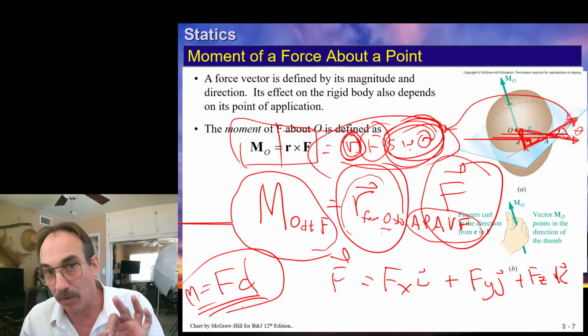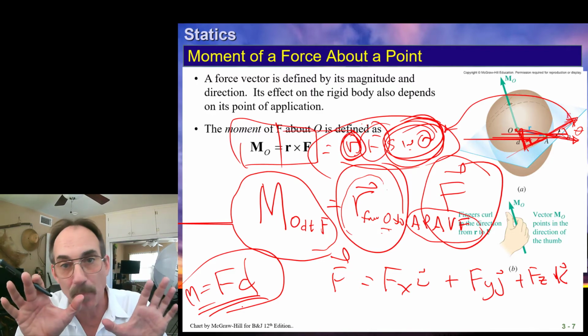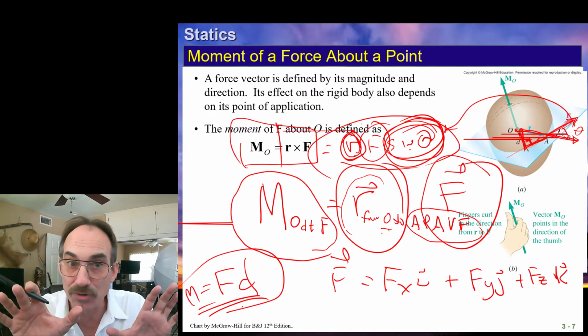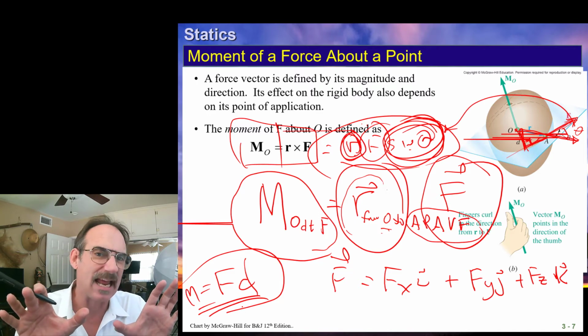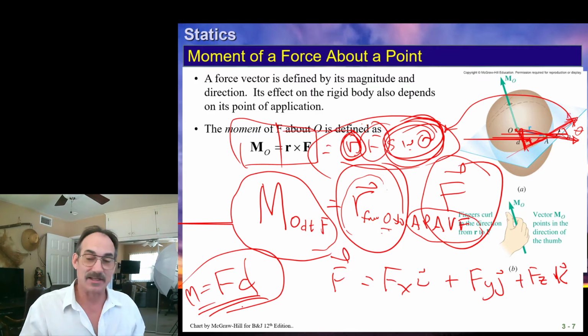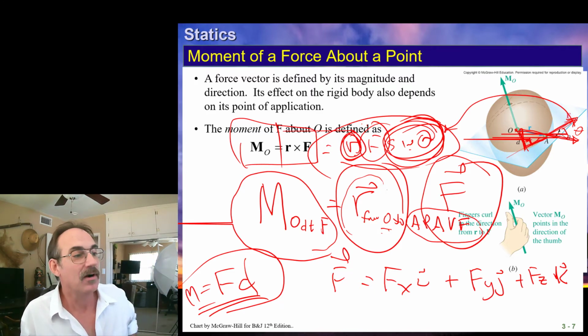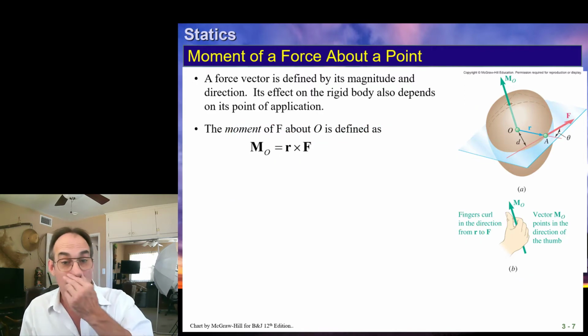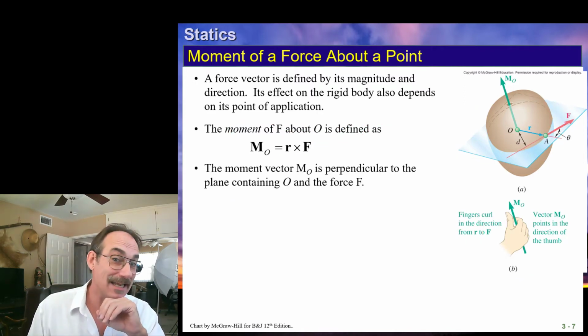And as you develop some proficiency, most of the practical problems you're going to see in aircraft analysis, and a lot of rocket analysis too, will be simple scalar analysis like this, force times perpendicular distance. However, when you do anything more complicated, you're going to need to understand cross products and dot products, as I keep saying.